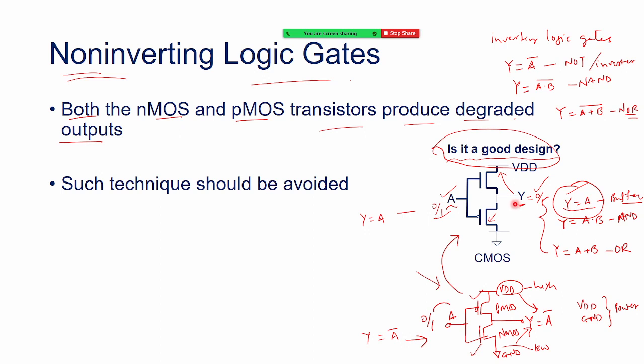We have always seen so far in all lectures that NMOS was the pull down network, responsible to connect or throw the logic low level or ground signal to the output when it's switched on. And we know that the PMOS transistor was in the pull up network, responsible to connect our output to VDD, logic high. But now we are doing the opposite, and we have declared that PMOS cannot be used to have a strong 0 and NMOS cannot be used to have a strong 1.